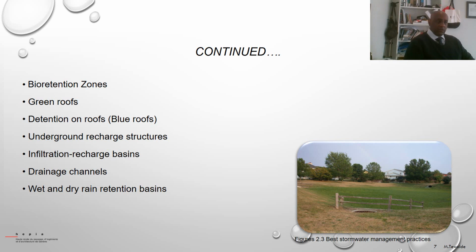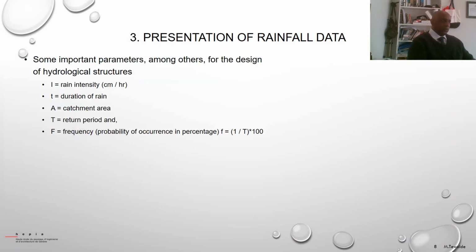And the dry pond is something like this one, which holds the water for a certain period and releases it, just simply to reduce the peak discharge. That is how we manage the runoff in urban areas, so that we decrease the effects of inundation and all those pollutions.